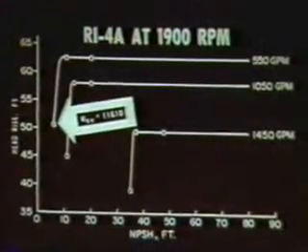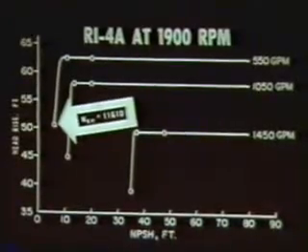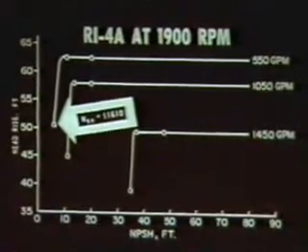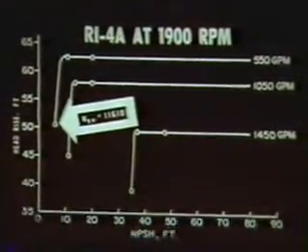The cavitation is localized on the suction surface at this highest value of positive flow incidence. Note the disappearance of the forward-swept cavitation with the loss of hydraulic performance. The cavitation has entered both splitter flow channels.